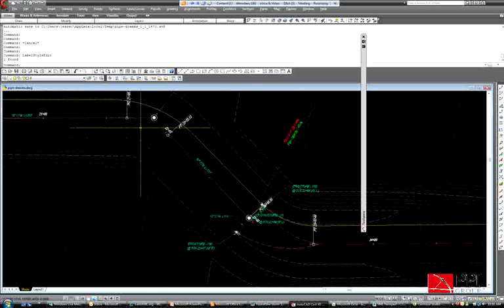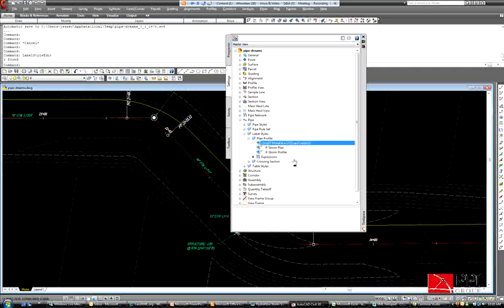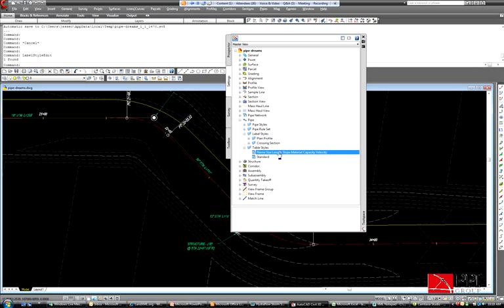So along with that expression, once I brought that expression in, you can see it's now available to my table styles too. I've created this table style with the name, size, length, slope, material, capacity, velocity. Kind of a long name. I don't know if that would pass many CAD managers, but that's mine.